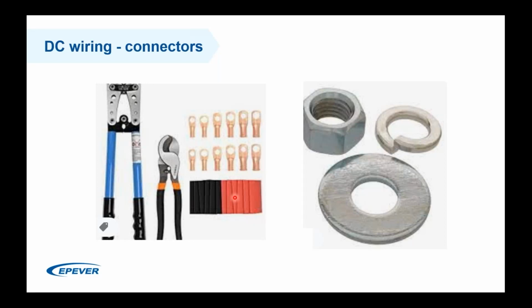Cable locks are used to connect the cable to a bolt, and it can be a battery bolt or a bolt on a bus bar. We will cover soon what a bus bar is. The cable lock needs to match the cable thickness. So you cannot use any sort of cable lock with any cable. You have to match them. Even the amount of insulation that you cut from the cable is important.